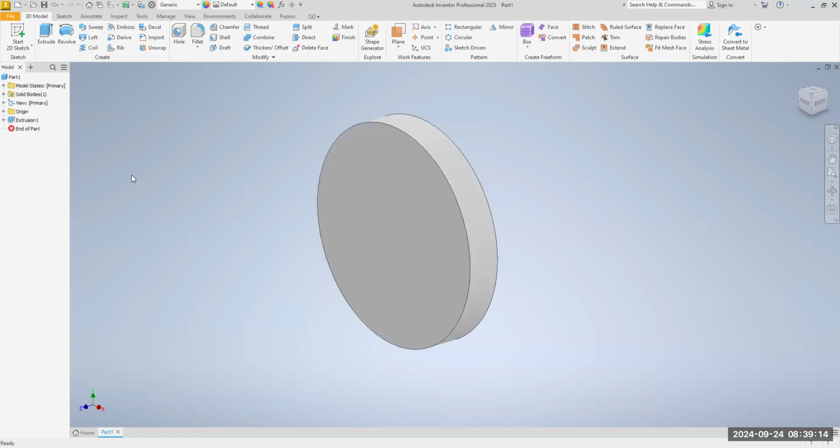Okay. Now, how come I like to extrude in the negative Z direction? Does anybody recall? Remember I said when you're setting up a CNC machine, you like the top of the workpiece to be Z0. And when you are cutting the material, you want to go in the negative Z direction, not positive Z, you're cutting air. Okay, you're cutting air with the tool. So to cut material, you're going to go in the negative Z direction.